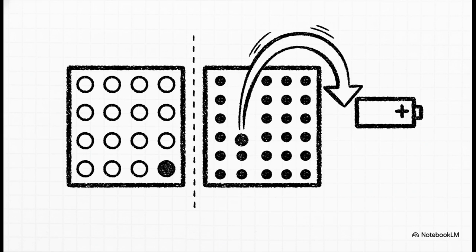Inside the LED, we have p-type doped semiconductors, which are packed full of empty positive charge carrier spaces called holes. Right next door is the n-type material, and that is highly concentrated with free electrons. Between them sits this default barrier called the depletion region. So when we push that 5 volts from our Arduino code, we are forward biasing the diode. We're applying an electromotive force that counteracts this default barrier.